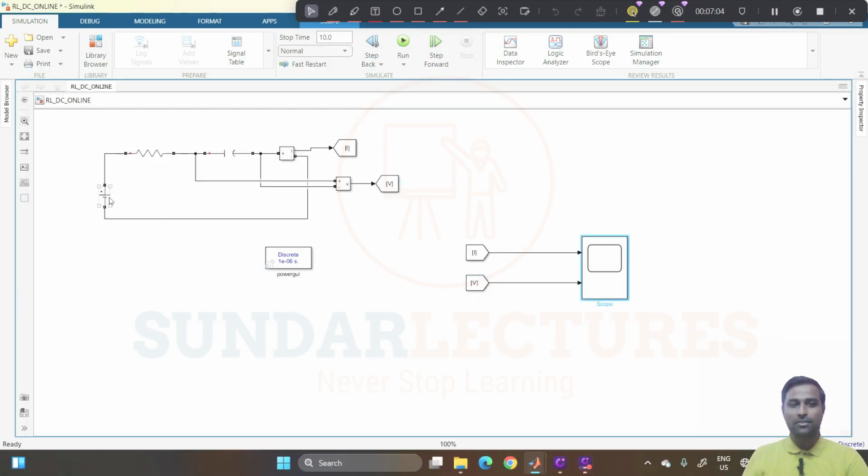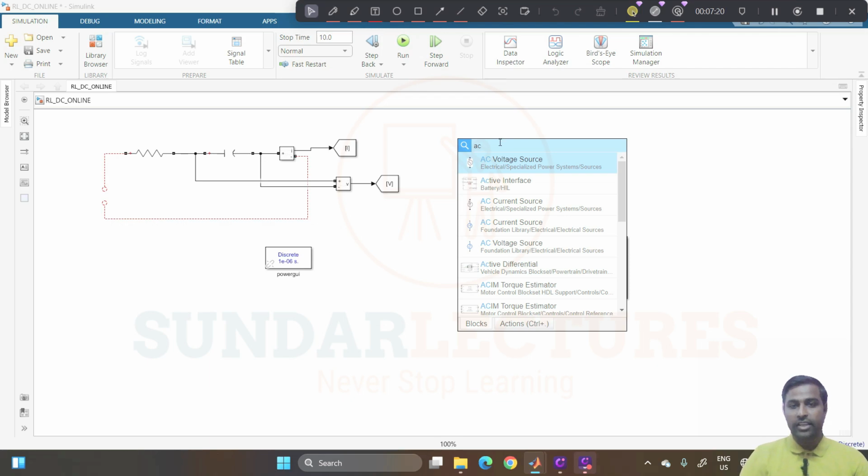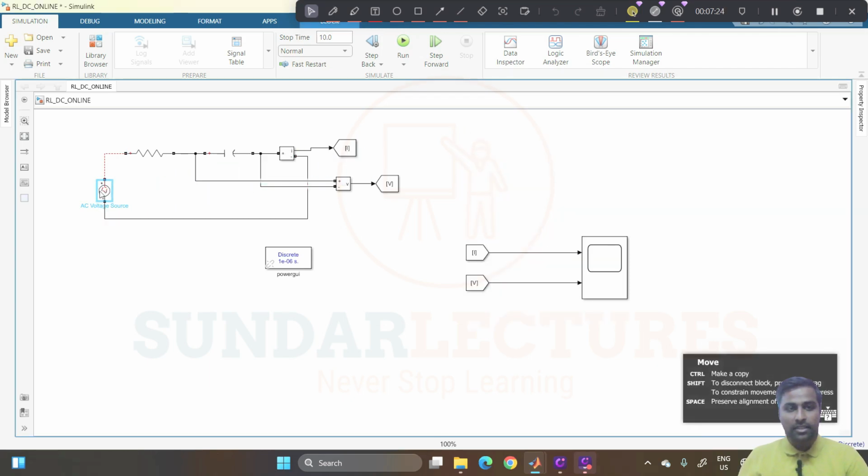You just change this one to AC. What you do? Just delete this and then double click here. You will get an annotation. Create annotation. There you can see AC source, AC voltage source. You can get it like this, and you just connect these 2 points.